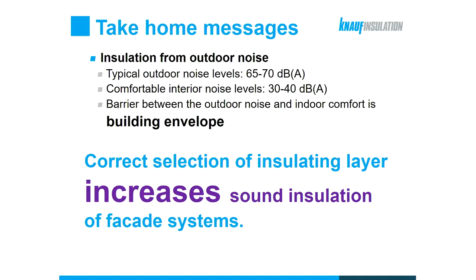And the building envelope is that element which actually presents the barrier between outdoor noise level and indoor level of acoustic comfort. With several real-life examples and actual constructions, we have also outlined that the correct selection of insulating layer increases sound insulation of facade systems or even reduces the level of rain noise. But on the other hand, we also did see that an unfortunate selection of insulating material can sometimes lead to a reduction of sound insulation.